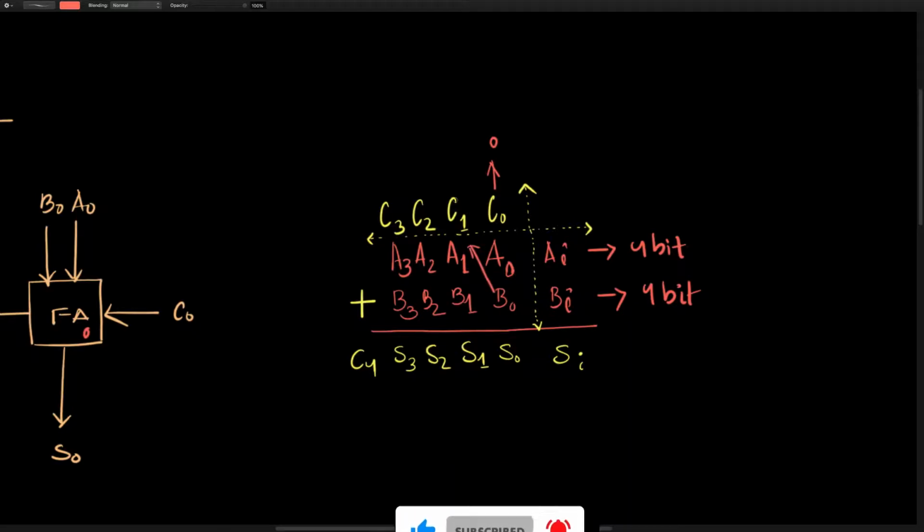For the next bit calculation, the summation is s1, and obviously we have to use a full adder here to implement this 3-bit addition. Here we can use a full adder with the carry being 0, or we can simply use a half adder to save resources. In the very same way we use a full adder here and also here. From the final bit calculation you may get a c4, that is a final carry that will come back in your result.